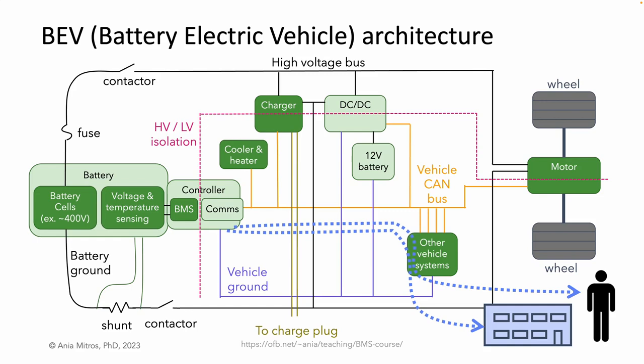As another example, if we lose a cell voltage sense wire, we don't have an immediate safety issue, but it is unsafe to charge, and the vehicle may warn the driver to please head to a safe destination and call for service. For internet-connected or cell-connected applications, the system may issue an alert or send data back to the manufacturer. Some of that data or alerts may come from the BMS.